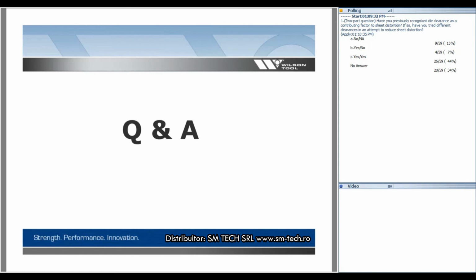Can I share some specific examples where I've seen random programming hit location decrease distortion? This was a case where the customer was creating a part. So they had nested parts, but one of the parts had a variety of holes, just a perforation window, if you will. Similar to what I showed on screen, it was a whole bunch of holes near each other.